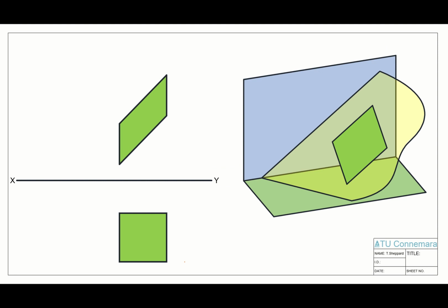The first thing we're going to do is take a horizontal line across our piece so that we can get our line parallel to the horizontal trace. So there is the line, the position I'm going to choose this time. You can see from my point here, there he is over here, and you can see he's going to be parallel to the horizontal trace in plan view. So we find him in elevation, which is parallel to the horizontal trace in elevation.